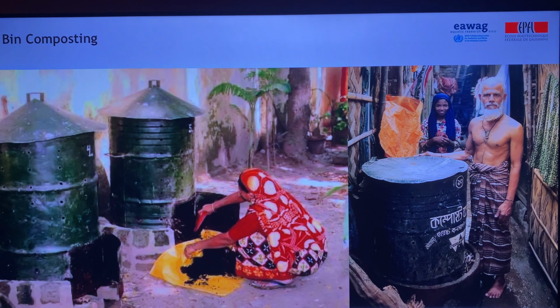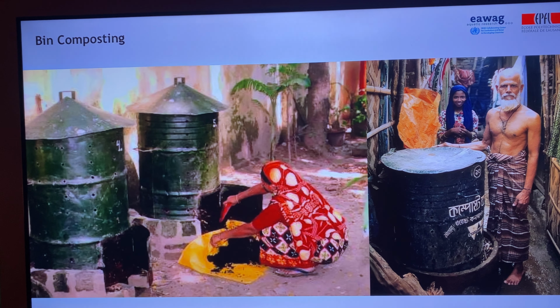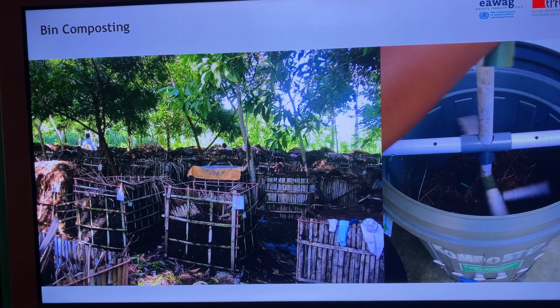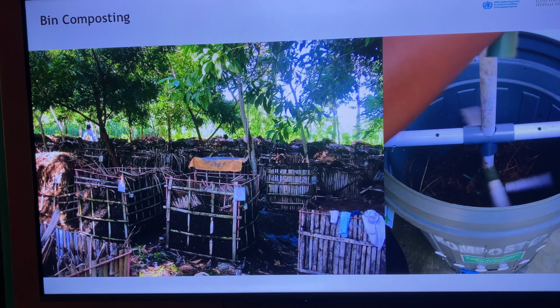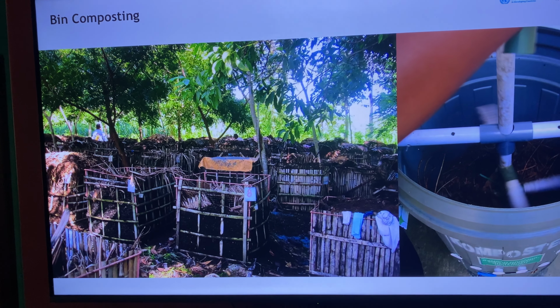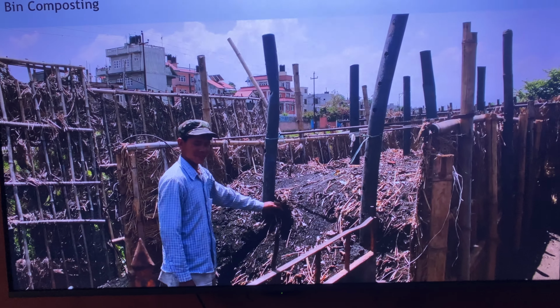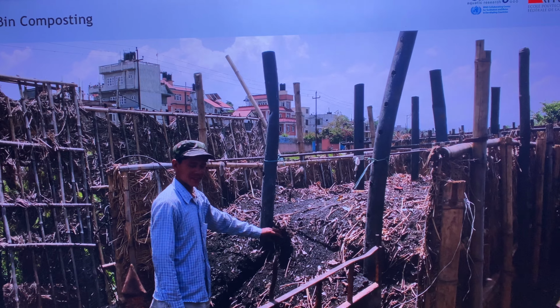And finally, our last technology is called bin composting. This technique is practiced mainly at household level, which will then treat small amounts of waste and produce compost for self-consumption. Biowaste is located in a container which most of the time has some sort of perforated wall for air to get through. Some containers include a stirring mechanism, as the one shown on the right. Bin composters can also be used on a big scale, as in this installation where we see passively aerated big-scale bin composting examples. In this case, the installations are run by operators, and most of the time the produced compost is commercialized.